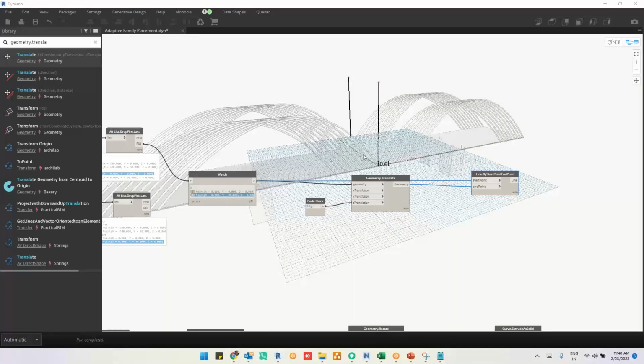So we can get the midpoint of this also, or else I can connect a line to this and get the midpoint of it and again use a translate. I'll connect these two lines and get the midpoint of this using curve dot point at parameter, and I'll use some sort of a sag.